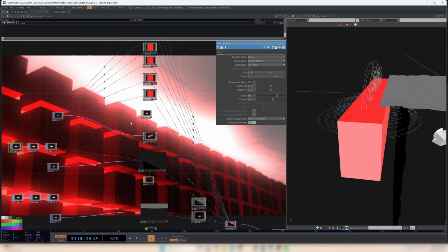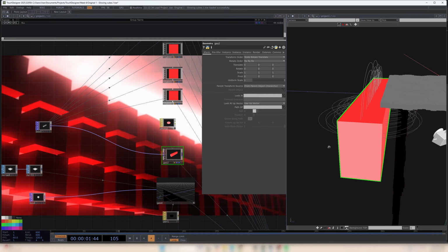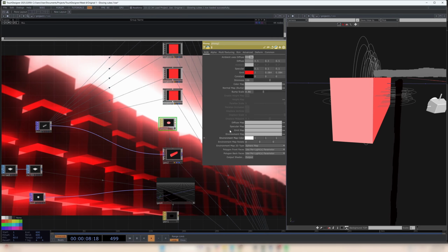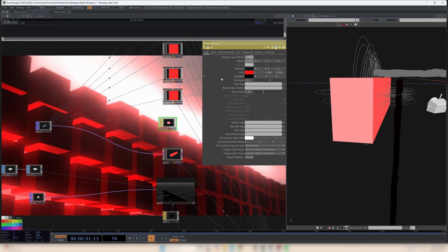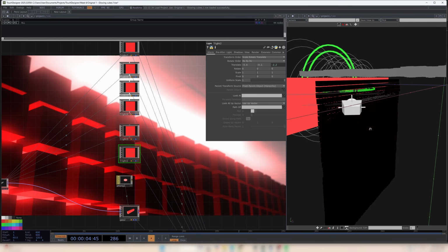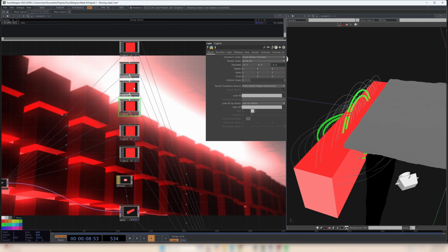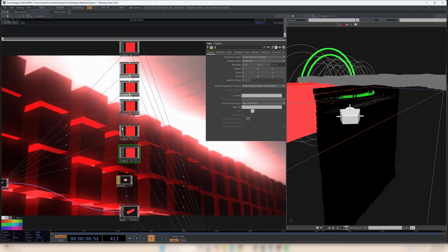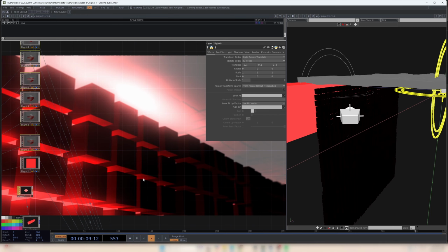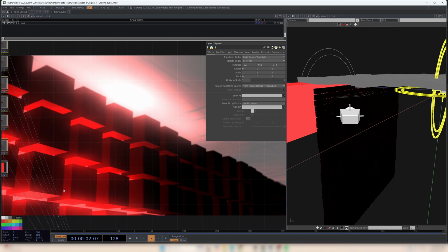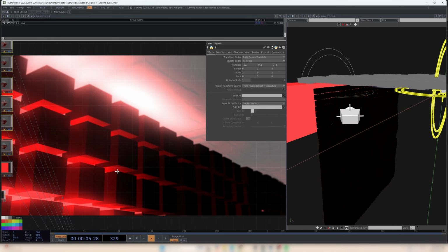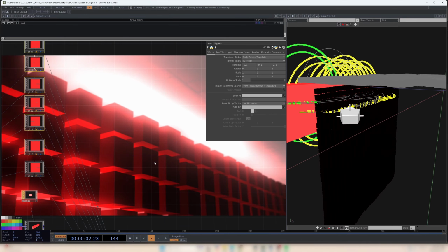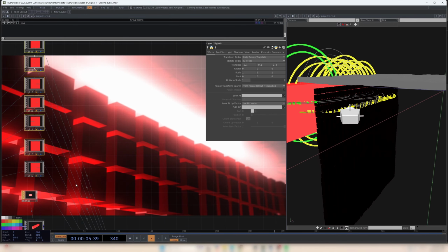Now the third piece of geometry which we included is quite literally just a rectangle, and we've added a Phong texture, used these settings you can see here, and then we've just put lights inside. I put a whole bunch of lights in because if you just use one light, it's only going to emit according to that light. With just one light active, you can see how it only emits from that texture where the light is. If I now add all those lights, you can see it's emitting down, and it looks more like the entire material is emitting light.